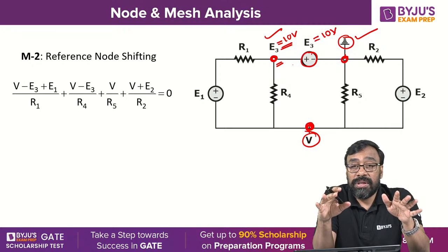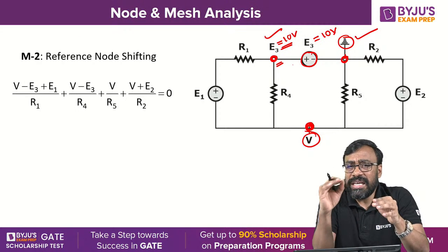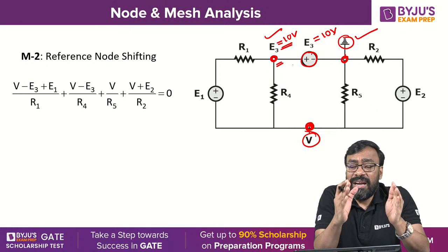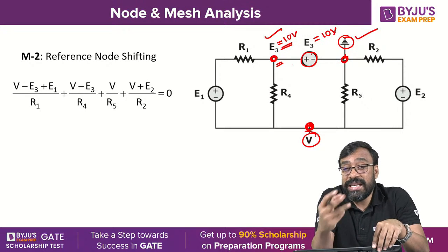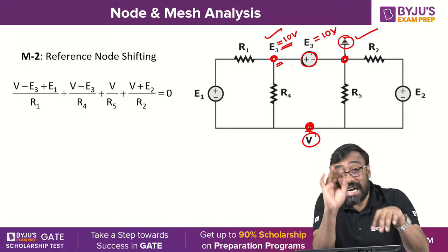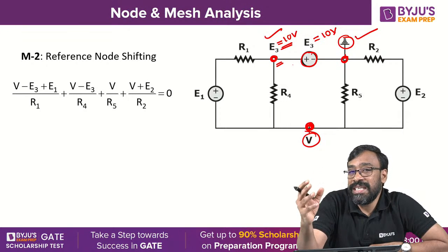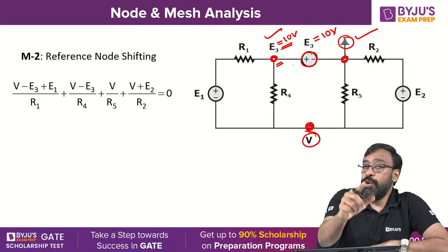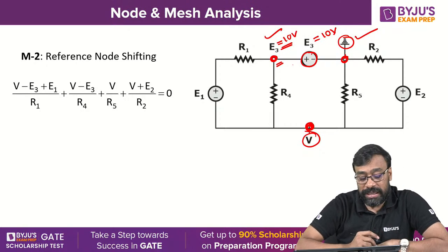You understand all of you? For n number of nodes, n minus 1 equations, that condition fails, especially when there are ideal voltage sources in the given network without any series resistor, Nana. That is very, very important to understand. So that is actually an advantage. Whenever there are ideal voltage sources with no series resistor, you should feel happy because the number of equations will reduce if you properly choose the reference node. You understand? Okay? Well, so look at this now.